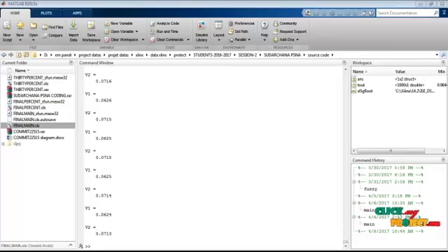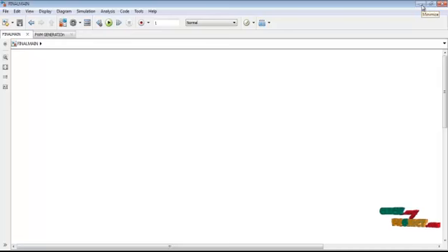Next we see the running process of our product. This proposed implementation is done in the MATLAB simulation environment. First open the MATLAB window and next create a new model file. After creating the new model file, we assign the elements as per the circuit diagram. We arrange the circuit diagram as per the paper. After that we connect the circuits and give the parameters for our requirements. After the circuit connection we click the run icon. After clicking that, the output waveforms are shown in the corresponding connected scopes.